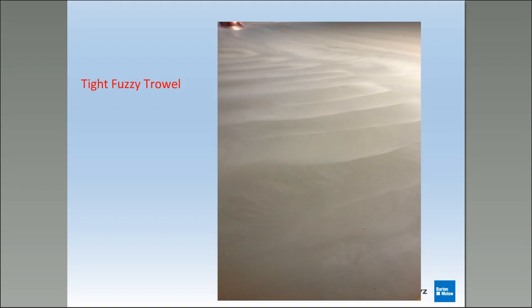Okay? Typically, this is what everybody loves to see if they're polishing. All right? A nice fuzzy trowel finish. This isn't hand troweled. I would avoid hand troweling if you can, because you can get slider marks and knee board prints. Those trails would be hard to take out with a trowel, and when you go to crack that surface open with a polisher, you'll magnify them and you'll see them.